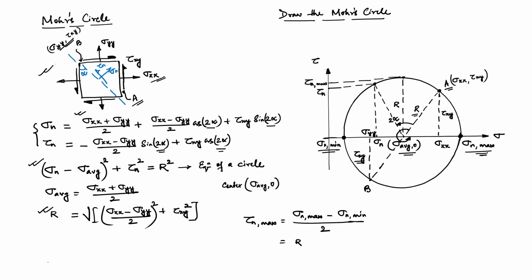For the designer, this diagram is very handy because the moment you know this stress field, you first develop this circle, and then from that circle easily you can identify all the component stresses.